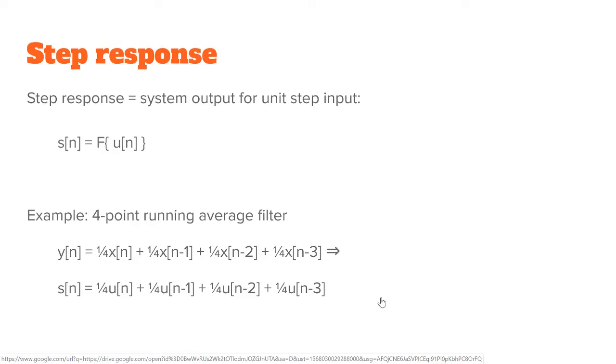How about step response? Same principle as in the impulse response. The step response is simply to take the step input and look at what the output is. That's usually marked as s[n], step response. It has less meaning than in analog systems because we can test the systems using impulse. On analog systems, it's not a good idea to zap the electronics.